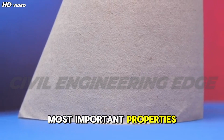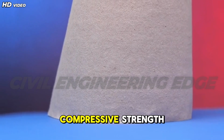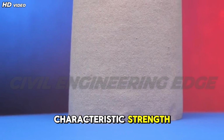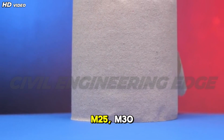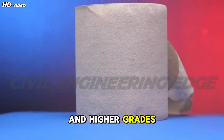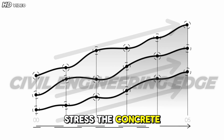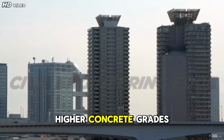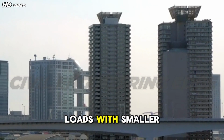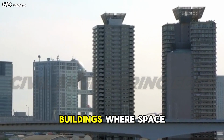One of the most important properties of concrete in column design is its compressive strength, usually represented by its characteristic strength, such as M20, M25, M30, and higher grades. This strength determines the maximum compressive stress the concrete can safely carry. Higher concrete grades allow columns to support greater loads with smaller cross-sections, which is particularly useful in high-rise buildings where space efficiency is critical.